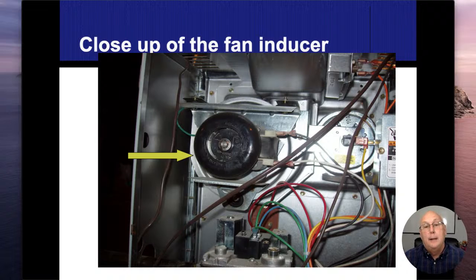All right. Now the computer doesn't know if the wheel is actually creating a draft or working at all, or the wires are broken, or it could be, I've seen birds stuck in these things and they didn't operate either. So if it's working and it's going to be creating differences in pressures, we're actually going to sense for that. So this cylinder device right here is called a pressure differential switch.